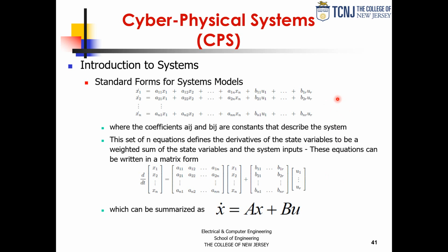For complex systems, what this tells me, I like it more because it's saying that if I identify the state of a system, the state variables, the derivative of that state, in a sense, what the system is going to do next, that's another way of looking at that derivative, is a weighted sum of all the state plus a weighted sum of the input. That doesn't matter what the complexity is, that is a way to look at system design and be able to come up with all kinds of applications of this idea, of this formulation, to be able to optimize systems.